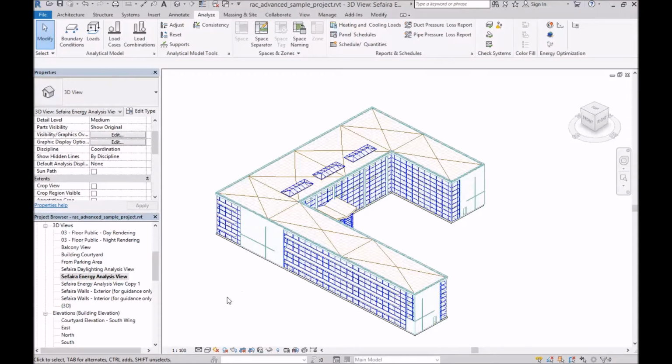The issue here has to do with analysis speed. Each additional plane, and especially glazing and shading planes, adds analysis time. Even if you never run into a scenario where a model is failing, the more you can simplify, the faster your model will run. So the following tips are going to be helpful regardless, just to make the energy analysis workflow as smooth as possible. We're going to look at three main culprits of plane count issues: curtain walls, window families, and shading elements.